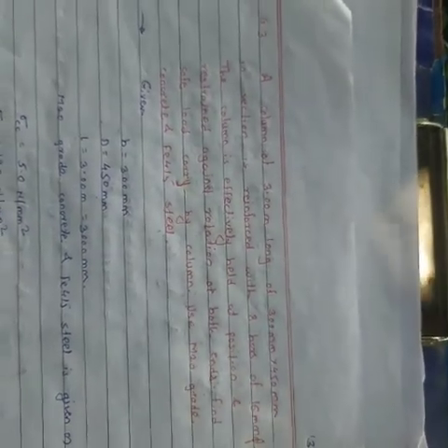Then you have to go for another problem, that is, now consider the next one. A column of 3 meter long having size equal to 300 mm by 450 mm in section, and it is reinforced with 8 bars of 16 mm phi, and the column is effectively held in position and restrained against rotation at both ends. Find the safe load carried by the column. Use M20 grade concrete and Fe415 steel. So in the given problem, what happened? The length of the column is given and the support conditions are given. It means that the column is effectively held in position and restrained against the rotation.